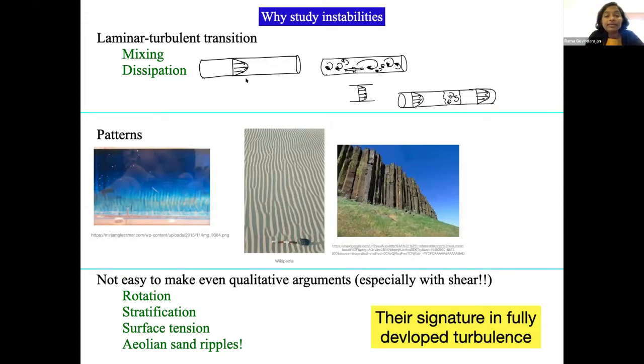Now, at low Reynolds number, this is what the flow looks like. At very high Reynolds number, this is what the flow looks like. So every blob of fluid goes through seemingly random activity, goes into completely arbitrary trajectories. It looks like, we'll see that these are not all that arbitrary. And then there are these structures which have drawn one streamwise roll, a roll which is aligned in the streamwise direction. This we'll talk about a lot tomorrow. So these rolls are a very important part of turbulence and of instability, and they're a very important part of any wall bounded flow. So we will talk about these in some detail, and we will see how we can make sense of this seemingly random flow.